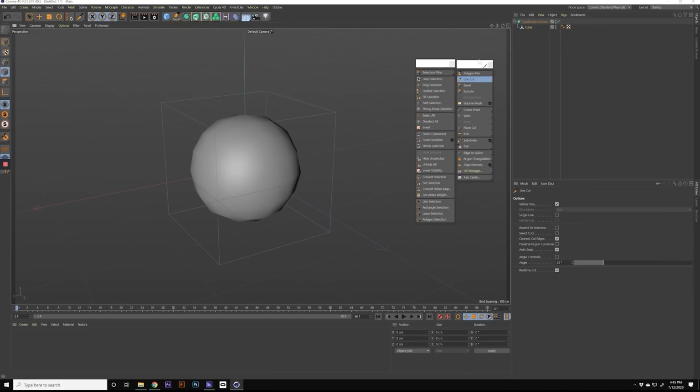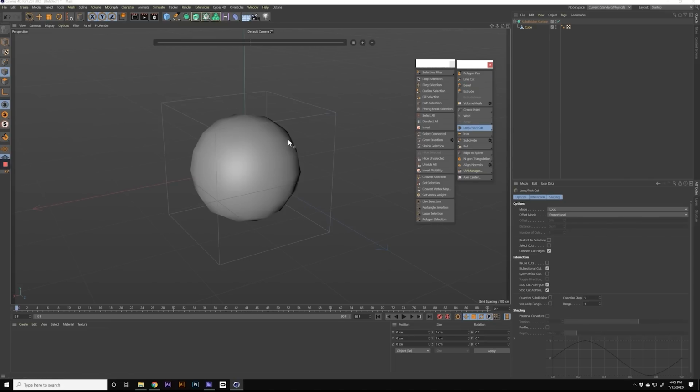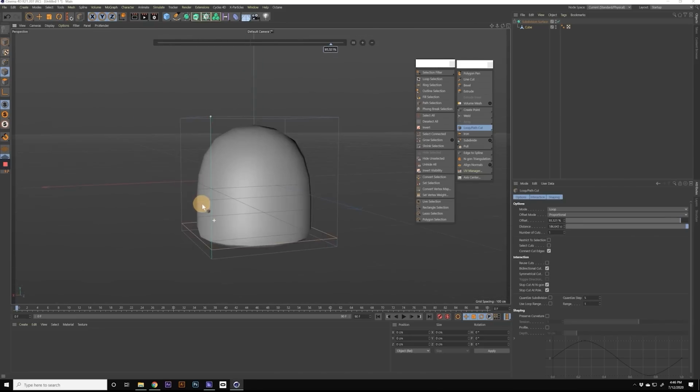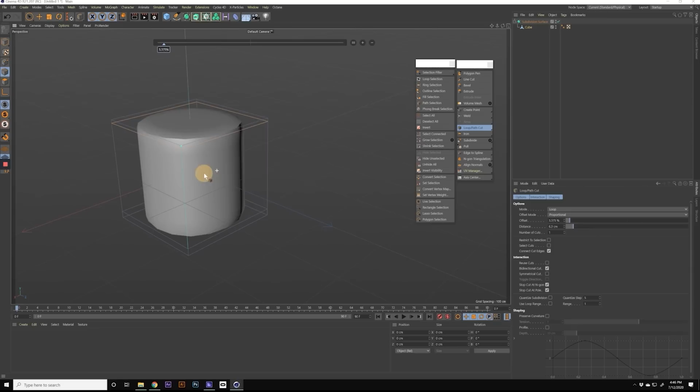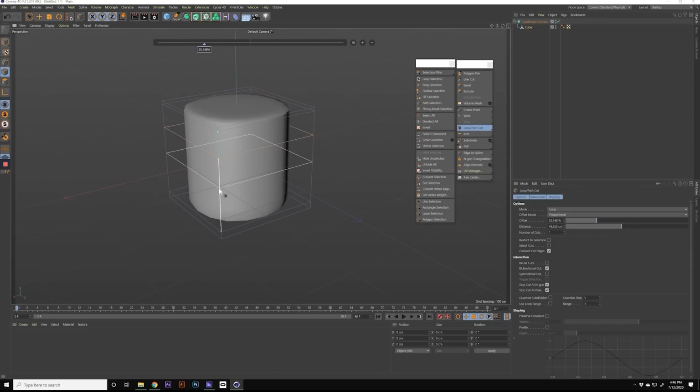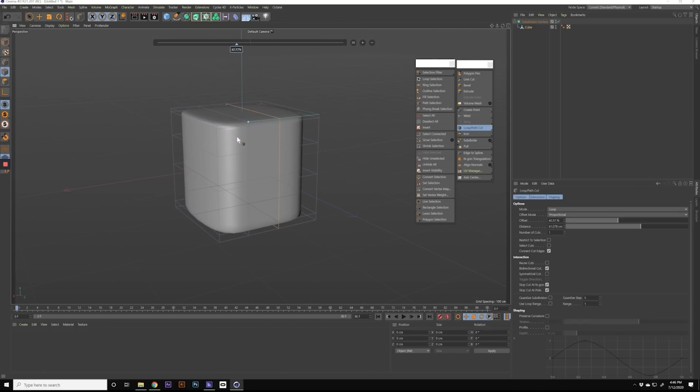So you drop the cube into a subdivision surface object, then you can come over here to your cut modes, and there's this loop path cut, or it could be KL or ML. I usually use KL because I remember K as in knife. So if you press K, you'll see your cut options. So KL is the loop cut, and you can cut the cube close to the edges to get this nice beveled edge. Yeah, box modeling, we're just going to cut around the square and extrude faces to create our hand. So let's start over.